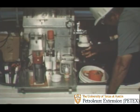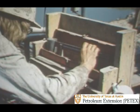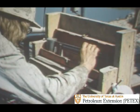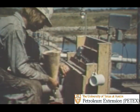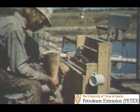Once drilling with the oil mud is underway, it's important for the mudman to make frequent tests on the mud to keep it doing a good job. The derrick man should check the density, or mud weight, with a familiar mud balance, and viscosity is tested with a Marsh funnel. The funnel viscosity of an oil mud is usually higher or thicker than that of a water-based mud of the same weight.